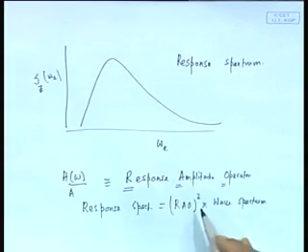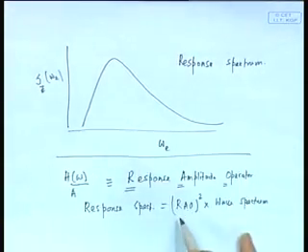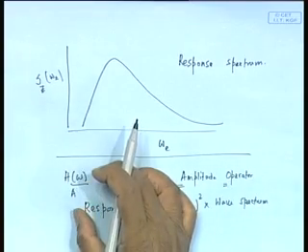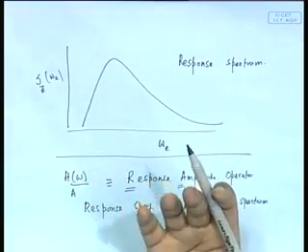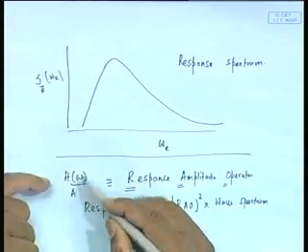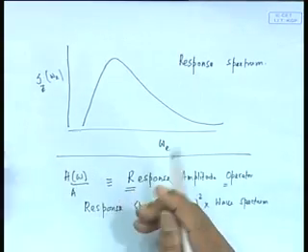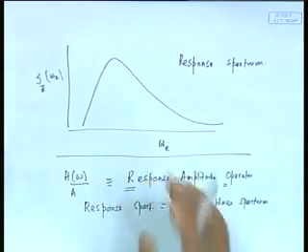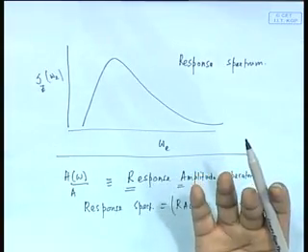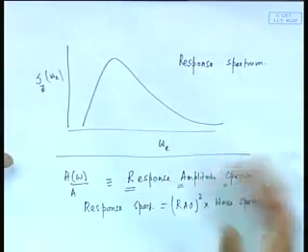Actually, here I want to tell you one thing, before coming to this part, let's keep it aside. Some people call this square itself as RAO. So, there is some kind of ambiguity sometimes. Technically I would personally prefer transfer function to be a better word, because in other literature, other subjects, they use the word transfer function. But historically in marine literature it has come to be known as RAO. So, we need to know this, everybody will say RAO.